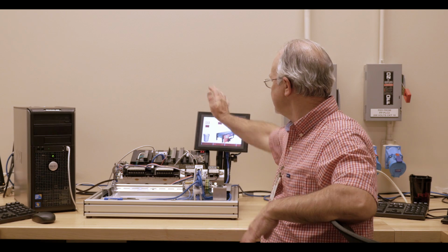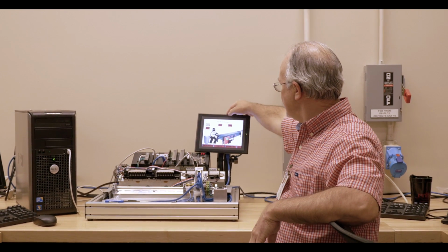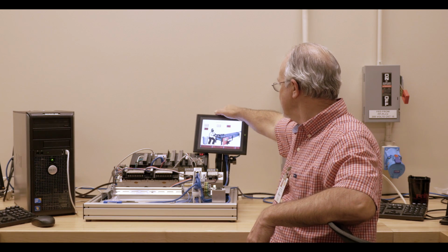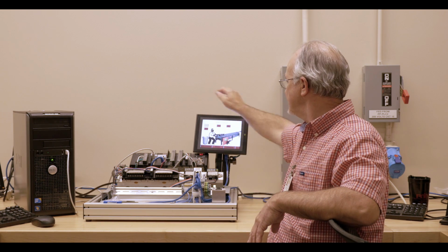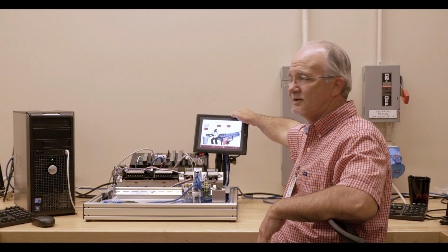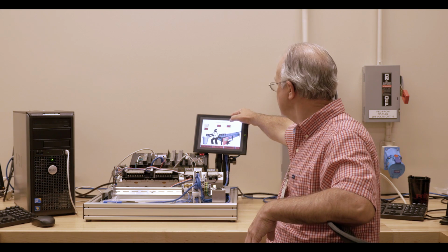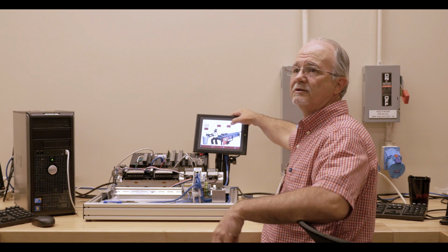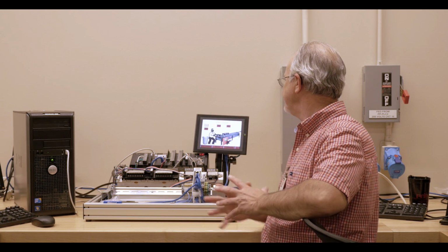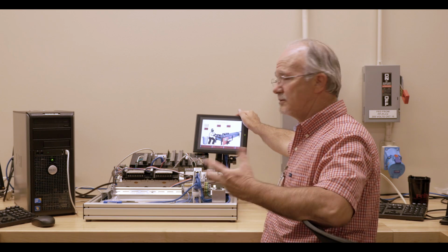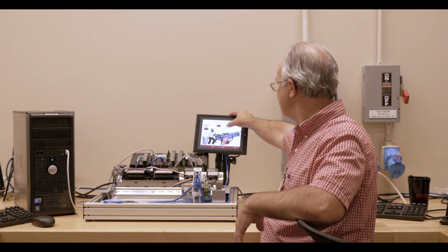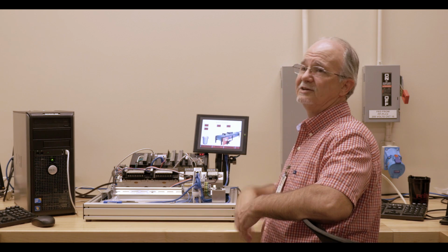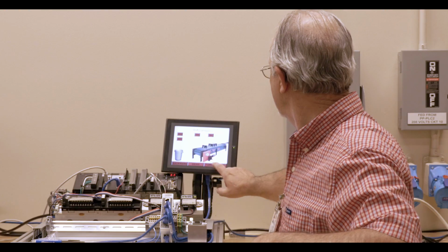We have a simple shift conveyor here. We have good boards. Every time we put a good board on the line, the operator places it on the conveyor. If we put a bad board on the line, the operator puts it in the trash. It's actually a simple increment instruction to keep account of how many good and how many bad. We've modified the program a little bit to include that if we get a total of 3 bad in a row, it turns off power to the line.